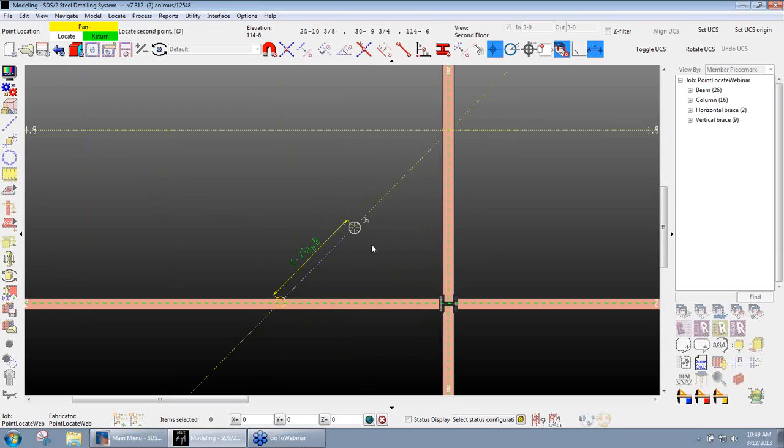And I said I wanted that to be at 15 degrees, right? So I'll just go ahead and type A. That gives me the at symbol at 15. And now as I drag that, it only snaps to a 15-degree line. One thing you're going to notice is as I'm dragging this mouse up along grid line B here, notice that my point also extends where I'm actually snapping to. So it's not necessarily along that same line as where my mouse is, but rather the distance from the first point to my second point, but at that 15 degrees.